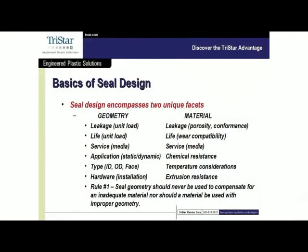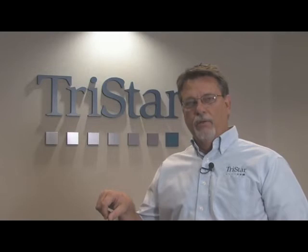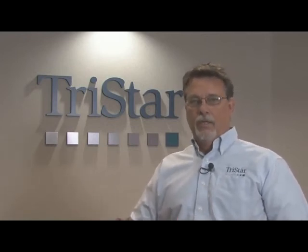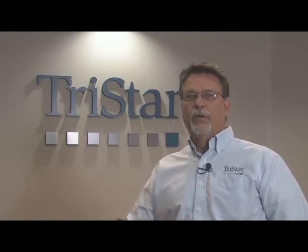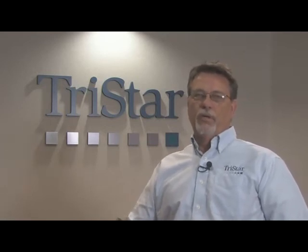So the number one rule I would mention to you here: seal geometry should never be used to compensate for an inadequate material, nor should a material be used with improper geometry. Basically what I'm saying there is don't use the geometry to compensate for a bad material, and vice versa, don't use a good material to compensate for a bad geometric design. You really need to balance the geometry and the material to be sure that you're getting adequate sealability, with low footprint areas, the lowest you can get away with. That's going to control your friction, that's going to control your heat generation, and ultimately your wear life.